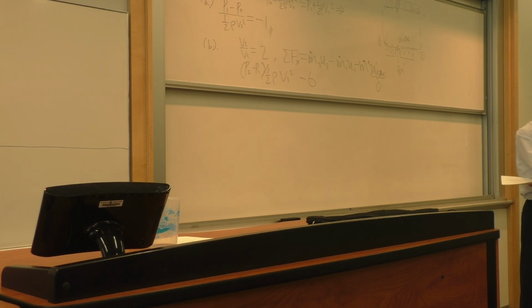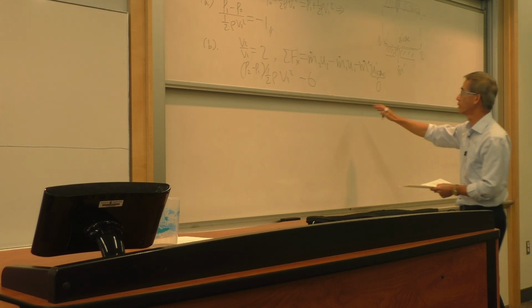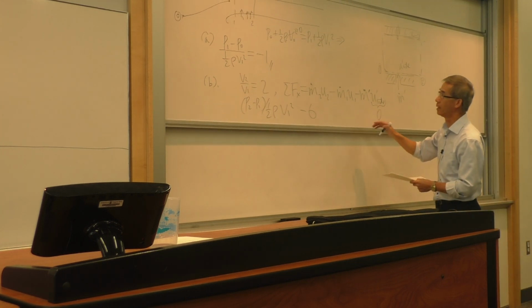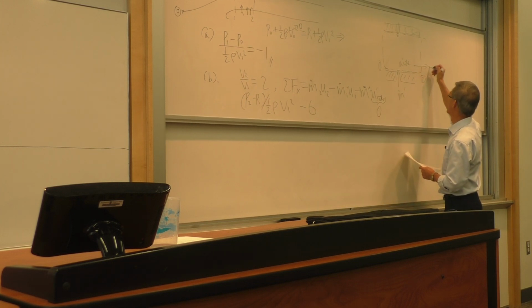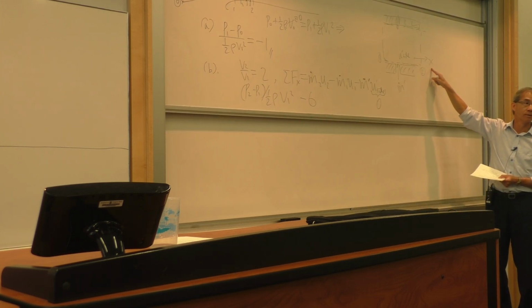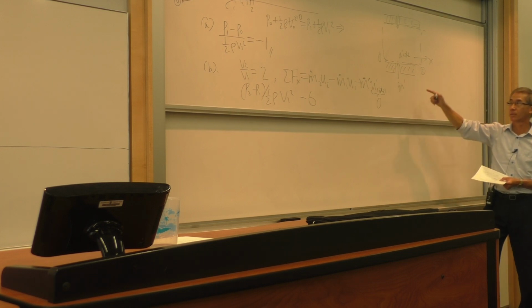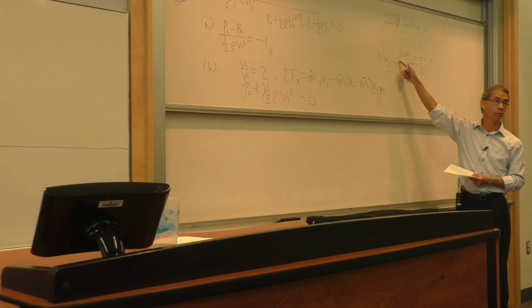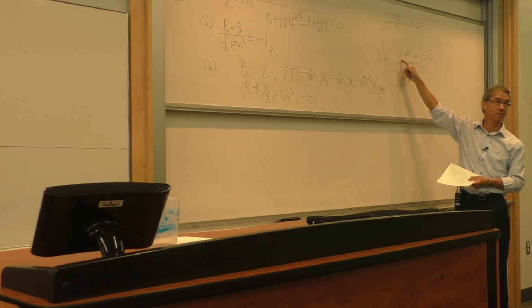Yes? Just to clarify, it's zero because it comes in perpendicular. That's exactly what we are referring to. Because why? The x momentum equation carries all the momentum flux in the direction of x, but as they enter, they are perfectly perpendicular to x, and hence they carry no x momentum whatsoever.